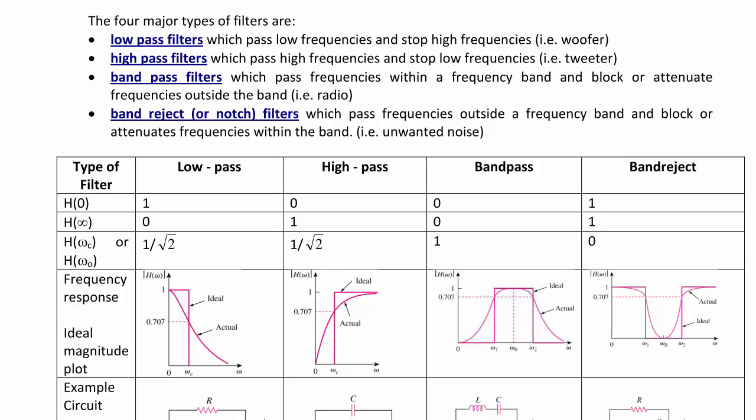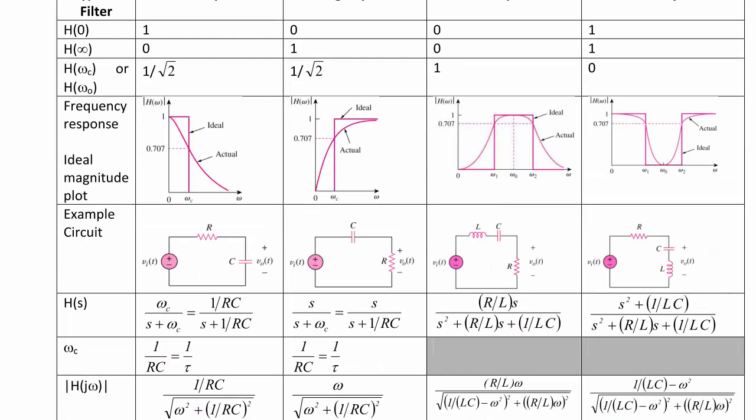So when we're talking about band pass and band reject, that center frequency is called omega naught, or the resonant frequency. And for low pass and high pass, at the cutoff frequency, we say the magnitude is decreased by 1 over the square root of 2, as we stated before. The following plot shows a sketch of an ideal filter as well as one of the actual filter. And what you see here is that we typically model these as squares when really they die off with some type of curve based upon the Bode amplitude plot.